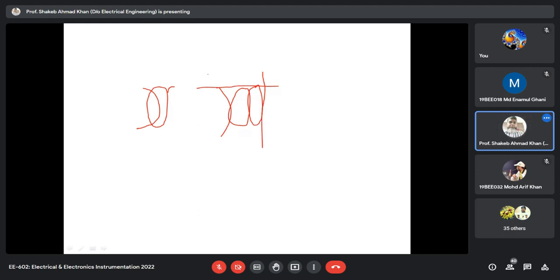Either we drive the vertical here or here. So this is counted 1, this is counted 1, 2, and this one is counted half, open 1, half. So it will be 2.5. And here in this case, it is 1, or we can count it as half plus half, so it also remains 1. So whenever you have an open-ended Lissajous pattern, the open end will be counted as half. Means when we are drawing the tangency, it will be half.